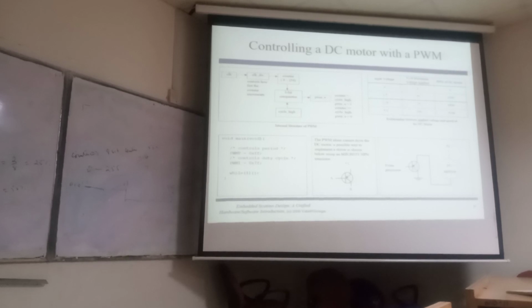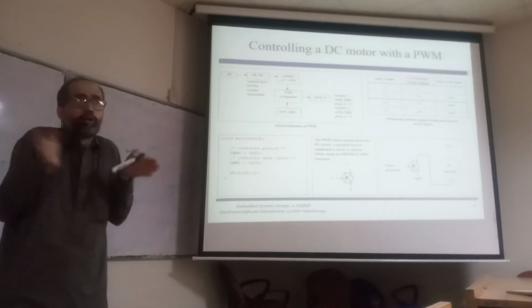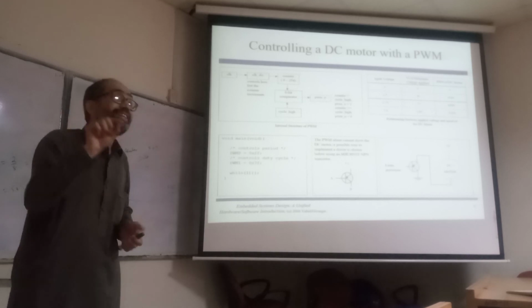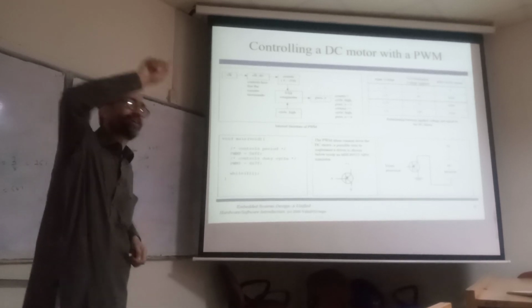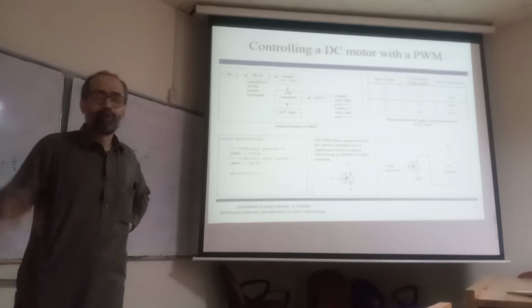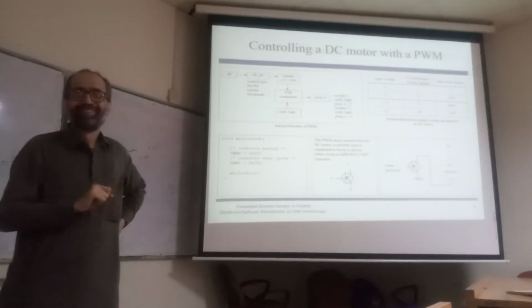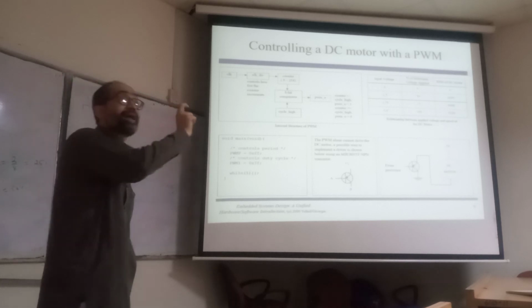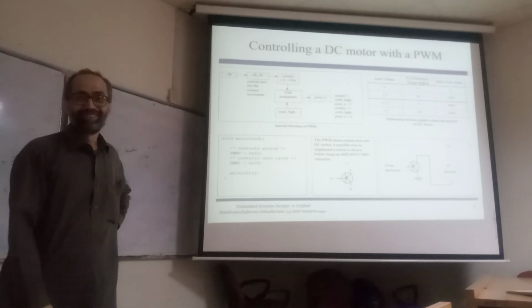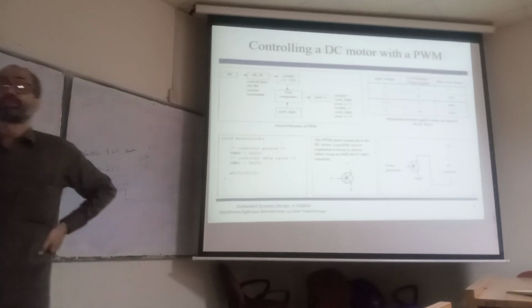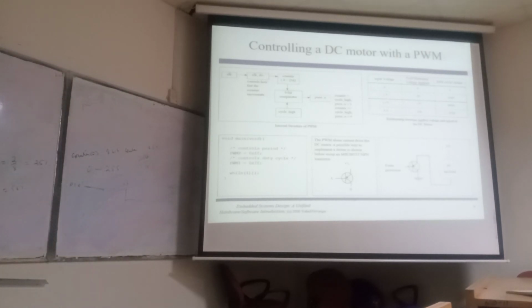There are also some microcontrollers that have internal timers, and you can configure those timers. Maybe there is one timer within a microcontroller, and you say, I want to configure this timer as a clock counter. I want to configure this timer as an event counter. I want to configure this timer as a PWM signal with a 25% duty cycle. There are a lot of configuration registers within the microcontroller, and you can configure these timers. These are dedicated timers.